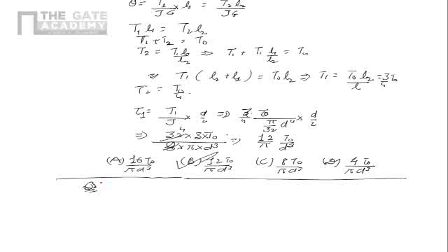So there is a spring like this, where the mean coil diameter is this diameter. That diameter is given as 20 mm, while the wire diameter itself is 2 mm. This is the 2 mm diameter of the wire. Now if the mean coil diameter is reduced to 10, the stiffness of the spring is approximately what?